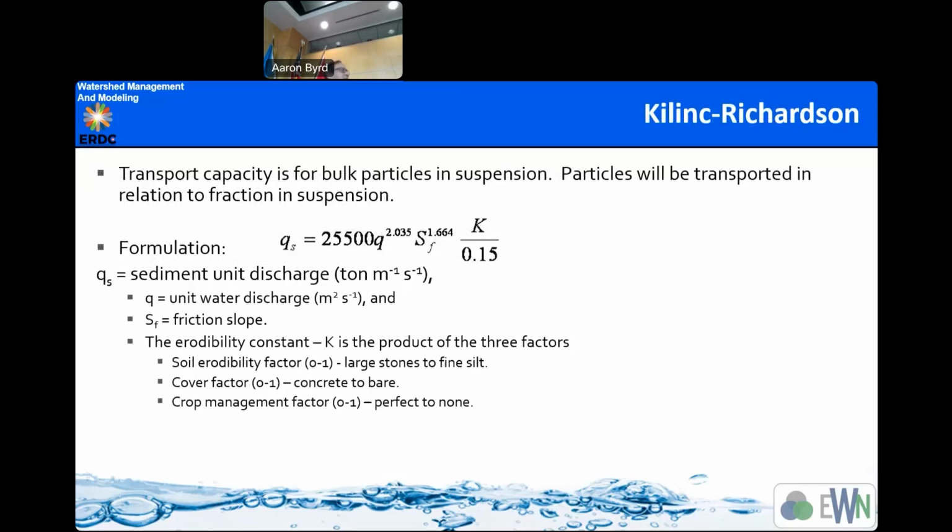For infiltration, the most dominant parameter is always the hydraulic conductivity, and we define it as a coefficient, as a calibration parameter. In surface runoff, the Manning's roughness is the dominating parameter. Likewise, in the sediment erosion process, the most dominant parameter is the scale, if you are using the transport capacity defined by this. So when we calibrated, we calibrated this K here, and then also that detachment K.